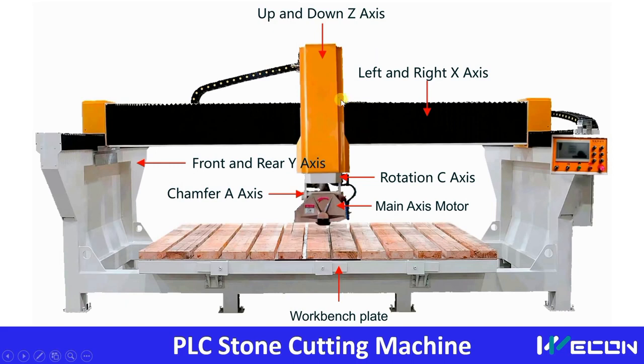Now this is common in every machine, but what is new in this machine? That is the A axis and the C axis. So here there is one main motor which only rotates the grinding wheel, or we can say cutting wheel, but the A-axis can rotate this complete assembly in 360 degrees. There is the C-axis also. Previously we have seen that right now this plate is vertical, completely 90 degrees to this board, but due to the C-axis we can make this wheel slanting. So we can cut slanting angles also.